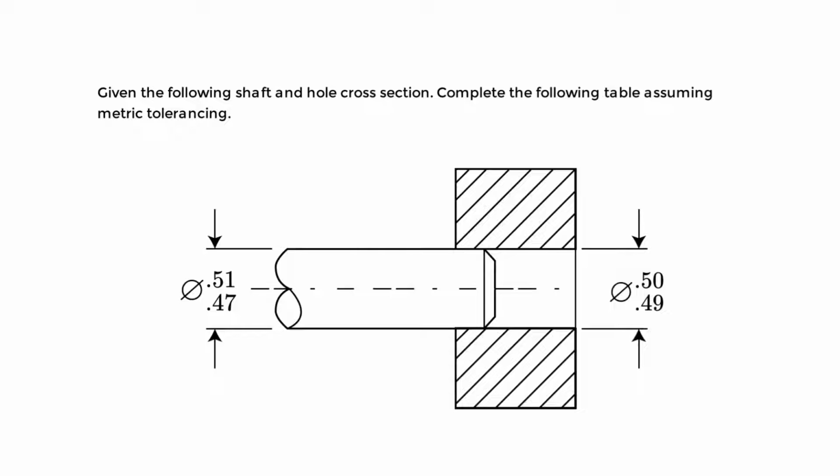So we know over time sufficient experience with common situations has resulted in the development of a standard, and the metric version is the newer and most commonly used. So the metric version specifically, I believe what they're talking about is the section under that on 442, and that's when you essentially look at the feature control frame and look at the LMC, MMC, the maximum material condition, and the feature control frame and the datums and so on. So that's what they're talking about there.